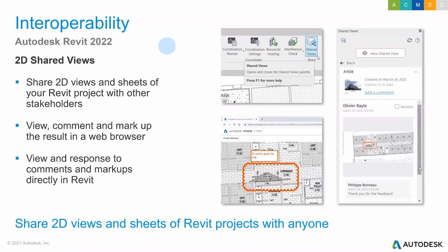Now, you might also be wondering, well, in what way are we sharing it? So Autodesk has their own browser-based sharing technology that they call the Autodesk Viewer. I think it's at viewer.autodesk.com from memory. That now is integrated a little bit more directly into their design tools. So in Revit 2021's case, we could open up a 3D view, share that up to the Autodesk Viewer, and then grab the share link and then maybe email that to a recipient. The recipient with their web browser can open up this shared information, which was formerly a 3D view, and they could do some markups on it and view it and so forth.